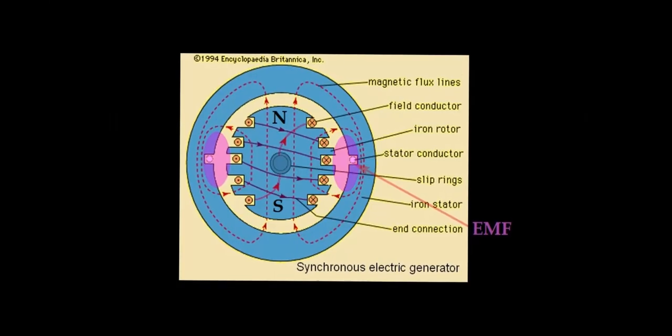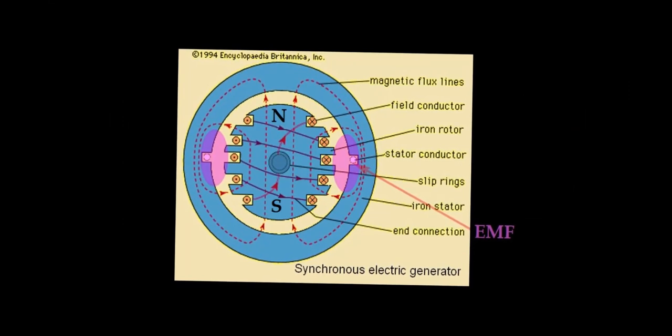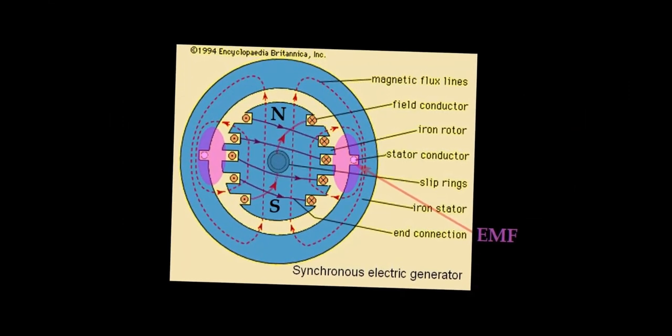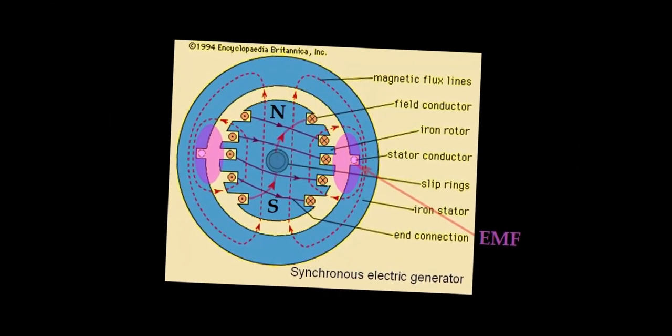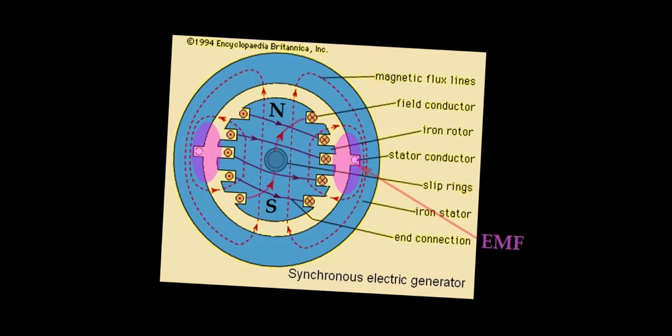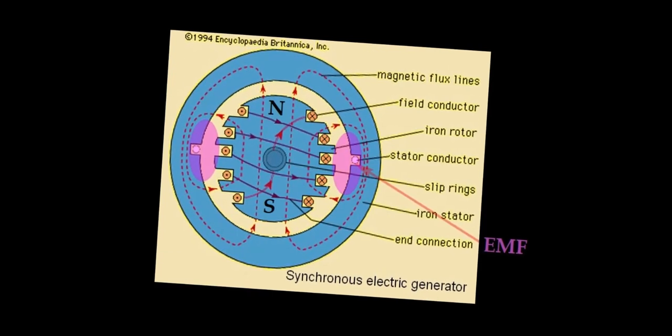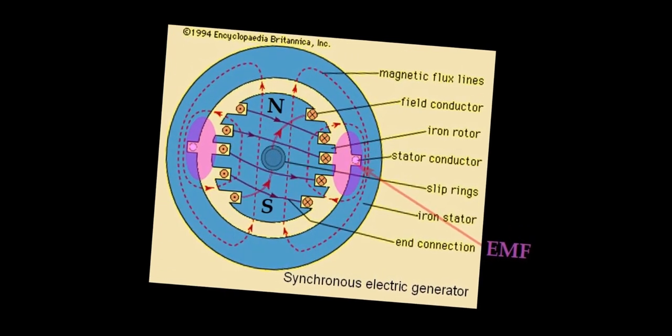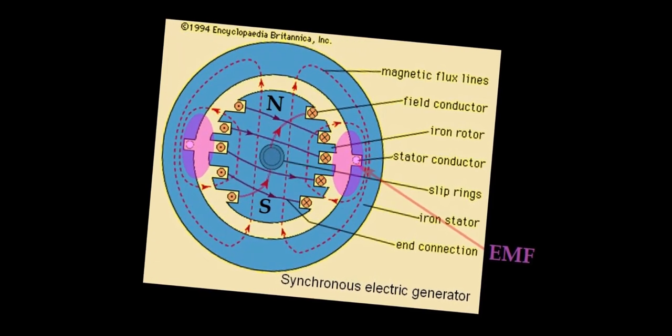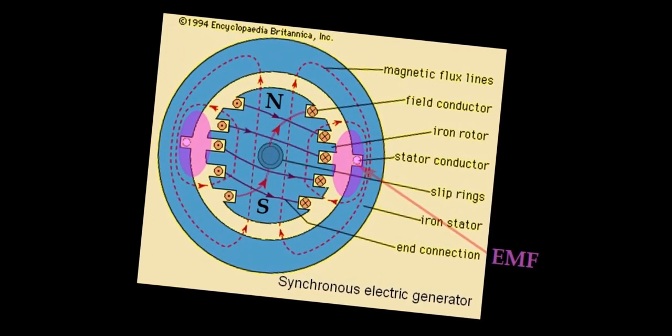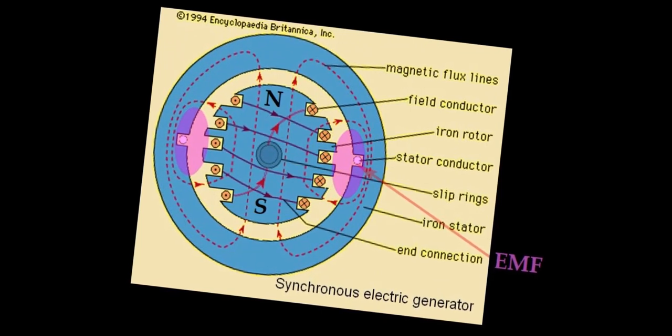Are the direct costs of generating magnetic flux equal to the output power when generating electricity? For turbogenerators, the excitation power is approximately 0.5% to 3% of the generator power. Let us ask ourselves whether it is possible to rotate magnetic poles with a static rotor core.